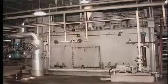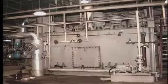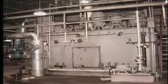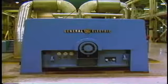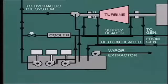In many turbines, the same grade of oil is used for both applications, so the hydraulic and lube oil systems are combined to utilize the same oil tank and the same pumps. The main oil pump is mounted in the front end pedestal and is driven directly from the turbine shaft. Diagrammatically, the scheme looks like this.